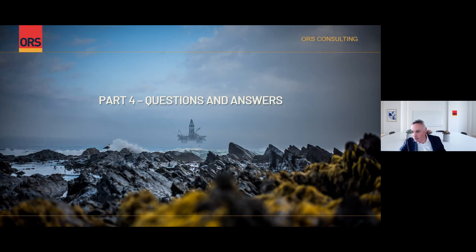On that one, there is one more question. It says, in the context of asset management, what are the main differences between FMECA and RCM studies, and when should which method be used? I would like to suggest that you should see the RCM part, like risk-based maintenance and reliability-centered maintenance, as an umbrella for different sets of studies, if you like. It's a portfolio of studies and collective efforts, where FMECA could come in in three parts. One of them is the highest level, where you do the top-down approach.